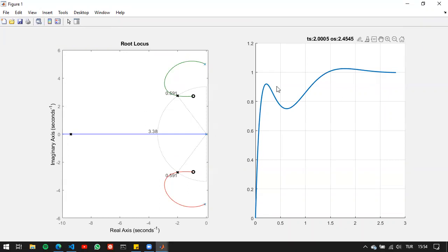And with tabulation, even though you could increase the number of points or the interval, it does not really help. All that we do in dominant pole placement or in tabulation is search for the best point that has the best settling time and overshoot values, but we do not succeed.